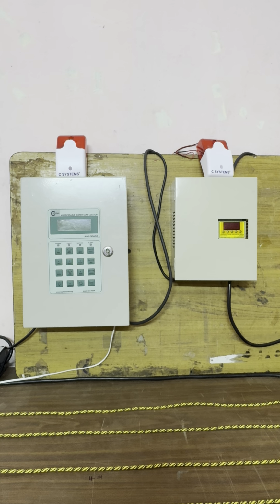You can see the water leak detection system in the display. It basically has three parts: one is the master panel, another is the module, and the third is the sensor cable. Our master panel model number is AWLD2400, and the module is AWLD M32. The master panel and module are connected through a two core 1.5 square mm shielded braided copper cable.